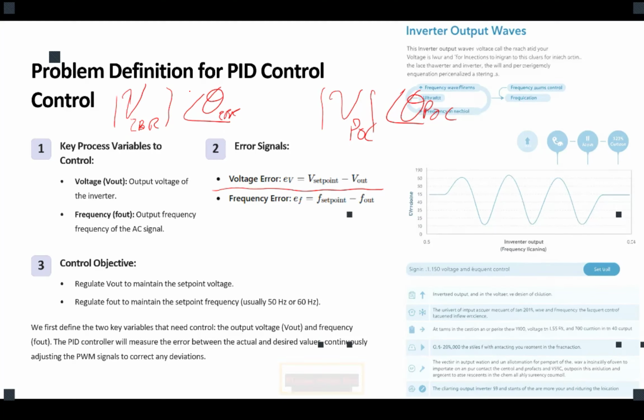So what we read at the terminal of the connection, the POC, that need is our destination. That defines our set point. And the current situation that we have at our inverter is our V out, or our current value that we have to push toward the set point that the grid demands. It is basically one of the reasons that we say it is grid following, because it has to follow whatever the grid demands.